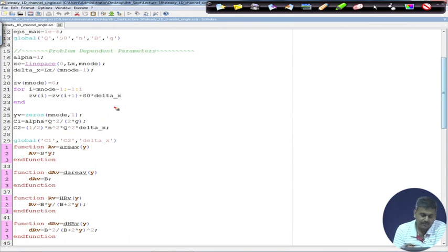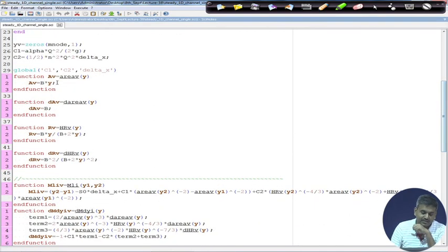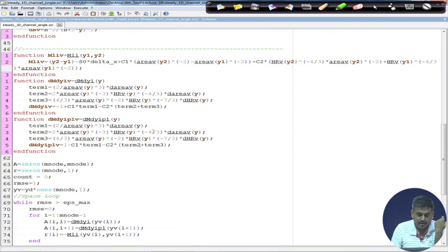Now, in this case we can define this C1 and C2, these are constant parameters. Interesting to see that for rectangular channels, dA by dy is B, R which is Ay divided by B plus 2y, and dR by dy we can directly calculate using this one. Now, we can define the equations for each segment.